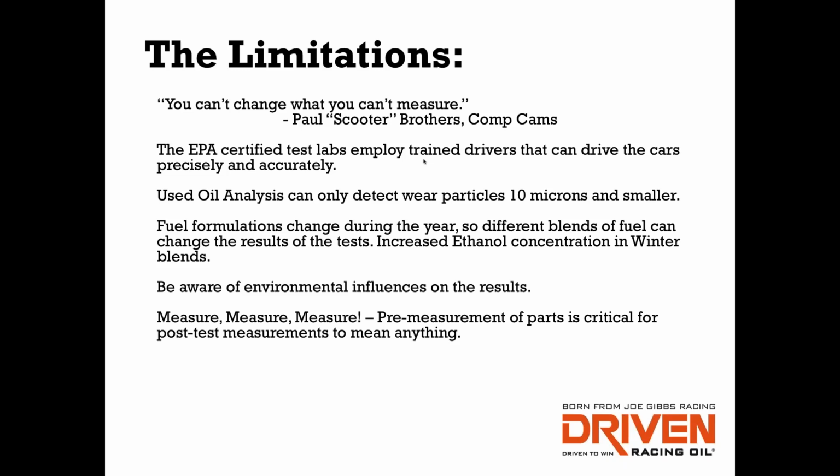It also changes how well the fuel atomizes, which affects air-fuel ratio as well, in terms of what it can actually burn. So you've got to watch out for the fuels. Really pay attention to the seasonality of the fuel, because I've seen it on the dyno from month to month with the same test engine. The peak torque values will change, and it's like, wait, hang on, what happened? Well, that changed because of the amount of ethanol in the fuel.